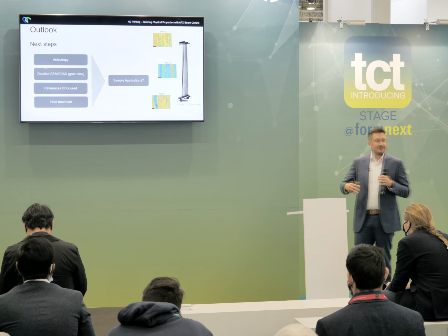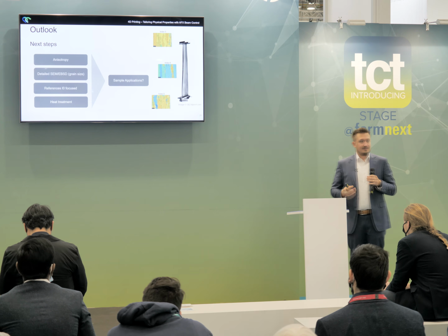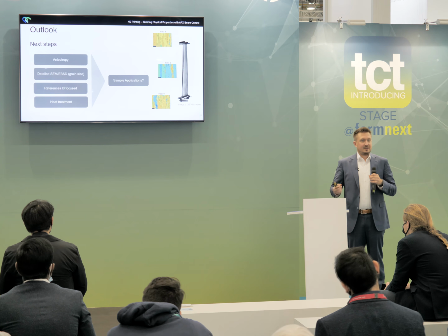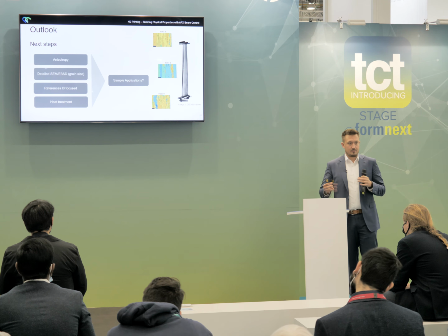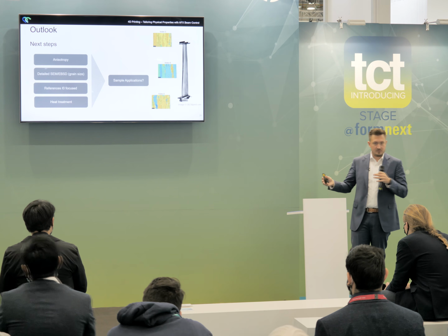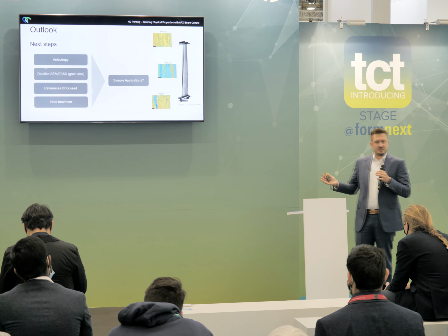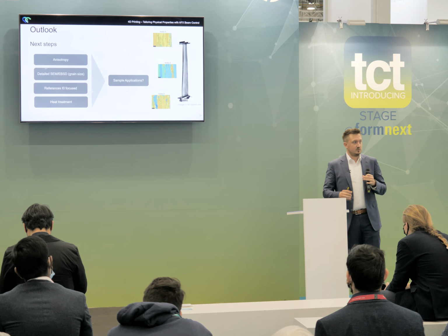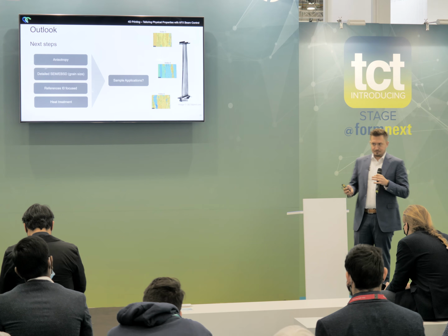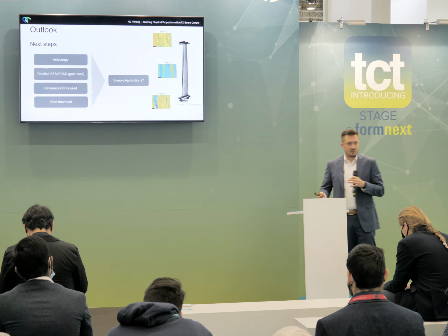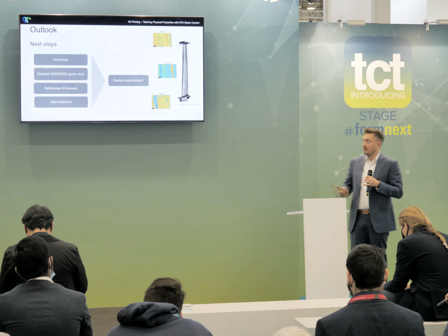But of course, we are not at the end of our work. So one very important aspect in that regard is that we look at the anisotropy of the mechanical properties, because of course it can be different perpendicular to the build direction. But even if it is, the typical load case is also not completely homogeneous. So we can use that knowledge to generate parts where we have different mechanical properties in different areas of the part, as shown in our vision on the right.